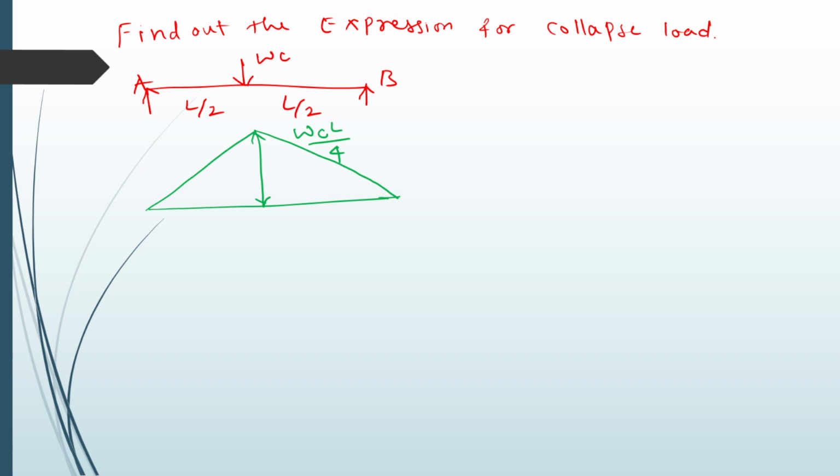By using the static method, the first method I am going to follow, we know that the total bending moment at any point equals the total plastic moment at that point.